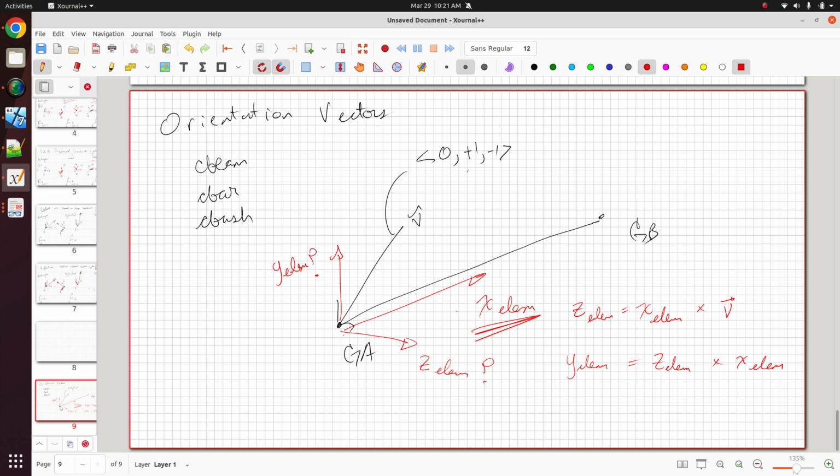Here, if we're thinking about this, it can actually get a little complicated. So I'll let you carefully ponder in what coordinate system we're viewing these different vectors. Here, I'm going to be assuming that the reference coordinate system is the basic coordinate system, CID 0, and the displacement coordinate system is also the basic coordinate system, just to keep things simple.